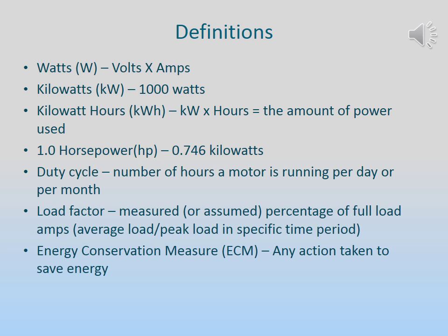Load factor: measured or assumed percentage of full load amps. When talking about load factor today, we are talking about a measured or assumed percentage of the full load that we are dealing with. In other words, if we have a motor nameplate that says 20 amps and we are drawing 20 amps, it is running at full load or its load factor is 100%.